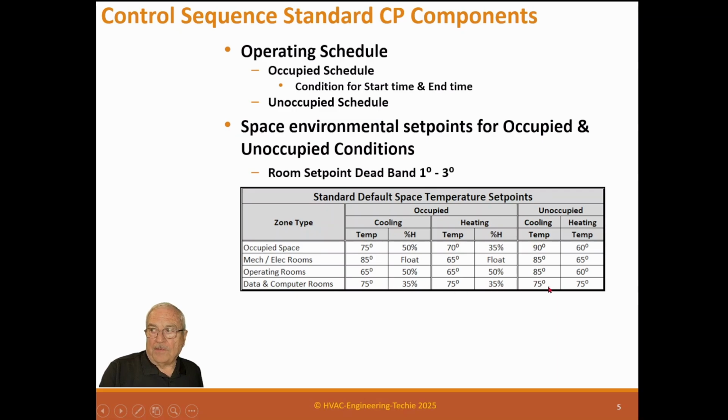Now they show 75 degrees across the board, but you might check that out, because nowadays data centers are in the process of raising their operating temperatures. They discovered, years ago, they thought that the servers needed to have 72 degree air, so we pumped 68 degree air down into the room to try to keep 72, 73 degree air at the server, which means the exit of the server. Well, nowadays they realize their servers will run up to 95 degrees, so they don't need that cold of air. So 75 is probably reasonable, but you might be able to get away with being slightly higher.